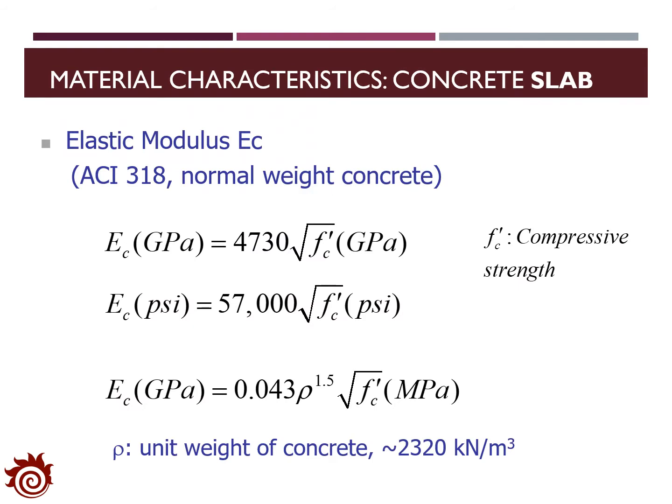In the estimation of the ESAL for the rigid pavement, we have to know the elastic modulus of the concrete slab, EC. Actually, in the AASHTO method, we assume that EC is a function of the compressive strength, which can be measured by a universal testing machine.